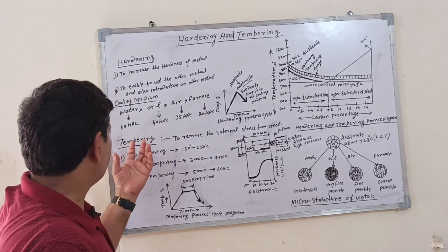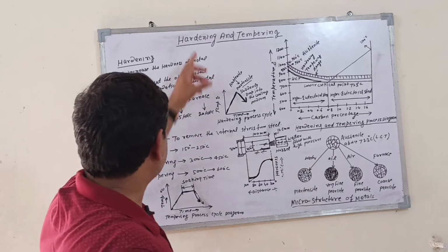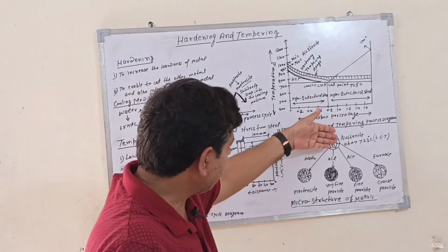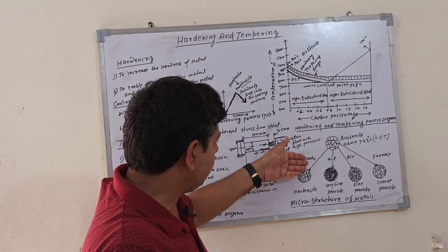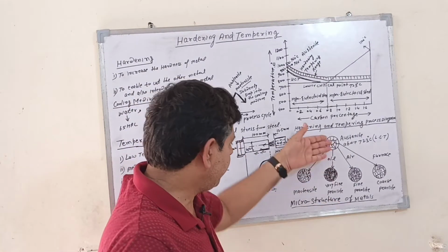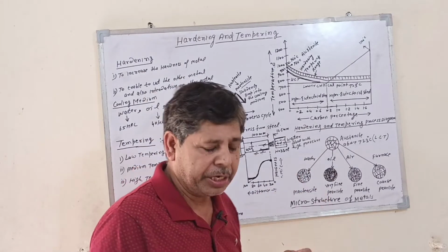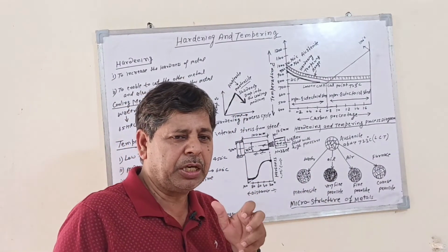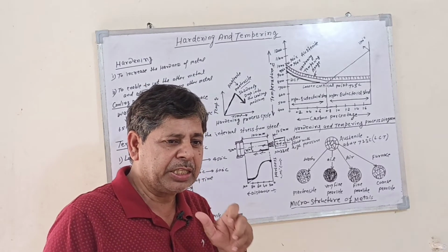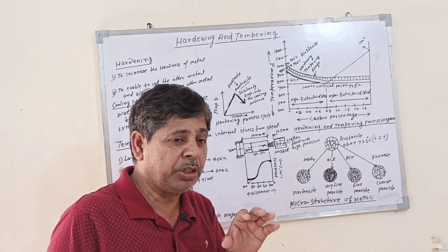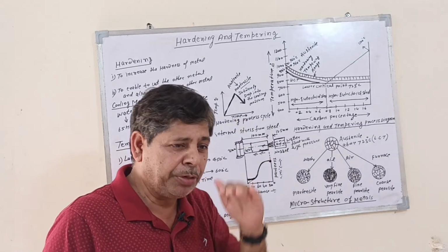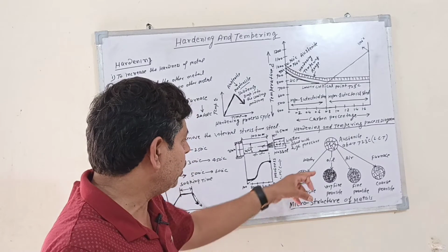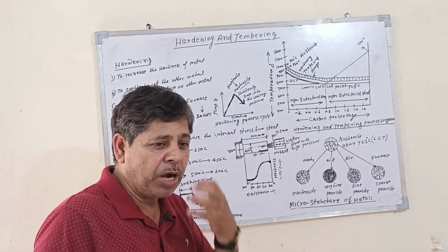Now tempering. During the hardening process, when the metal is suddenly dropped into water or oil, it changes into martensite and very fine pearlite. There is more chance of internal stresses being set up. Internal stresses are very dangerous for the material. When a sudden force is applied to the component, the metal will break due to the internal stresses. So how do we remove them?